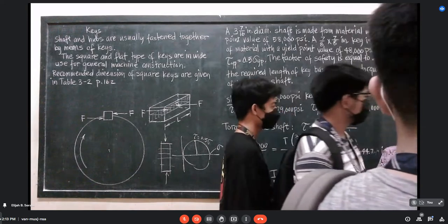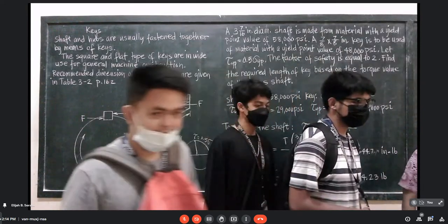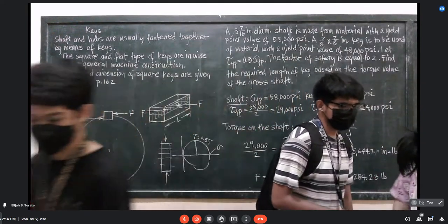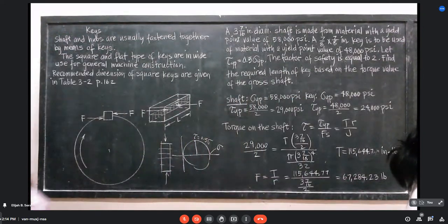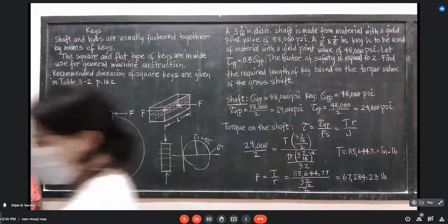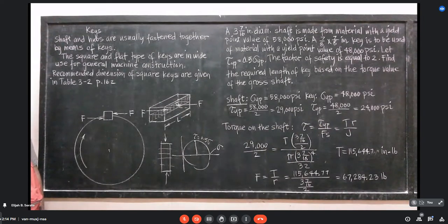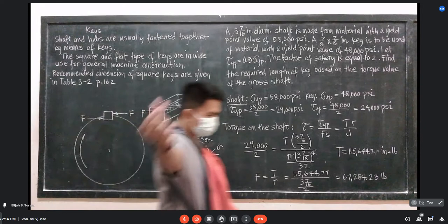Class, are you still there? Yes, sir. Did you hear our discussion? Yes, sir. Okay. They're talking about the maximum bending stress. You should use the c which will give you a maximum. So c on the outermost fiber, which has a longer outermost fiber. Good, yeah, of course.